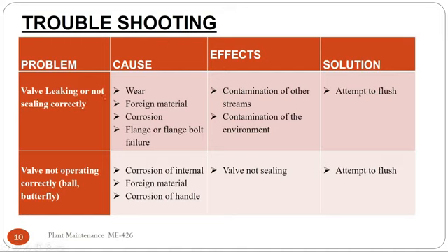Maybe the valve is not sealing correctly due to wear. As we know, as the time passes on, the chances of wear will increase. Or maybe due to the reason that you have selected the wrong valve for the wrong application. For example, we require a valve for petroleum products, and we have selected a valve for water, or the material is not compatible. Foreign material,